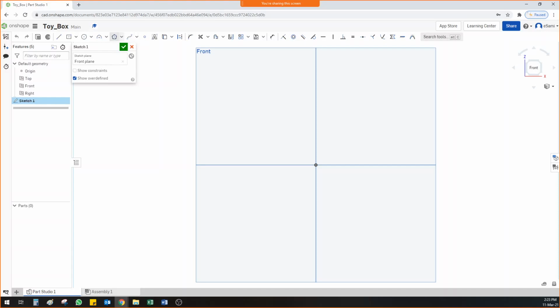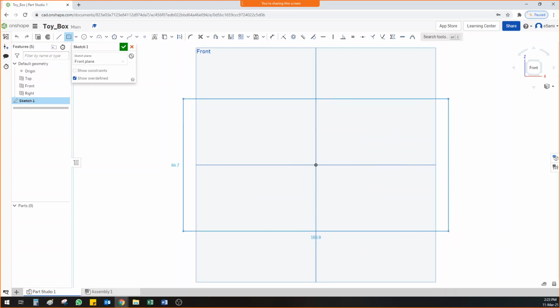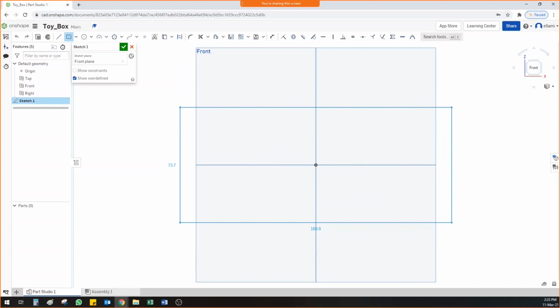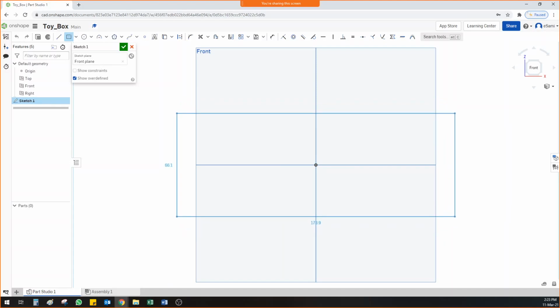So here, if you can see, the similar sketch tools came in. I can choose corner rectangle or center rectangle. So let me choose center rectangle. I'll choose the origin and start to move my mouse to make a simple box. You can see the units are also coming along with this box. So that's a good software. Some things in this are really good.